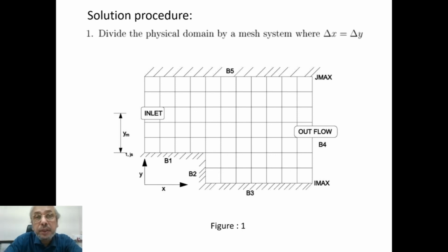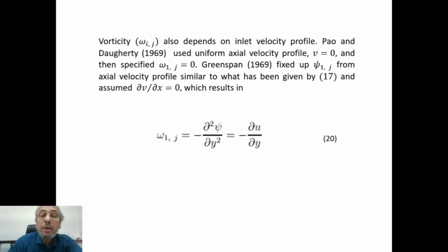You have to give boundary condition on all confining surfaces, but the boundary condition is not known, and the boundary condition has to be determined. But for solving the flow equations, you have to apply it physically in such a way that the boundary condition poses minimum disturbance to the flow field in the interior domain. And that is how we have gone.